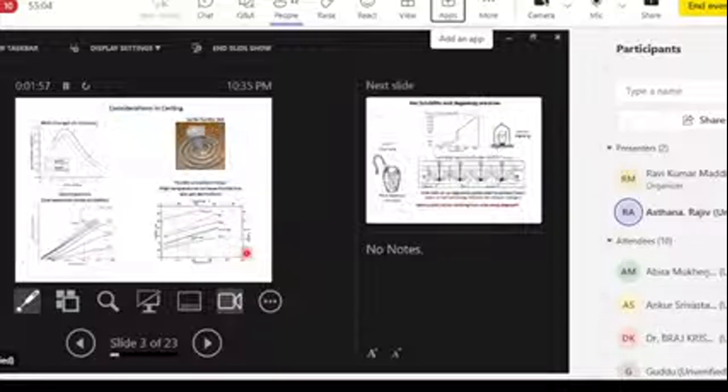So when you make a simple sand casting or sand mold, we mix, as you know, a base sand with some clay and water. The properties of molding sands are important because when you pour hot metal, there will be metal pressure and other things. There are some data over here that give us the strength of green sand as a function of moisture content. And we see that there is an optimum range of water that is needed to get the correct strength in molding sand. Very low water will not give you enough strength.